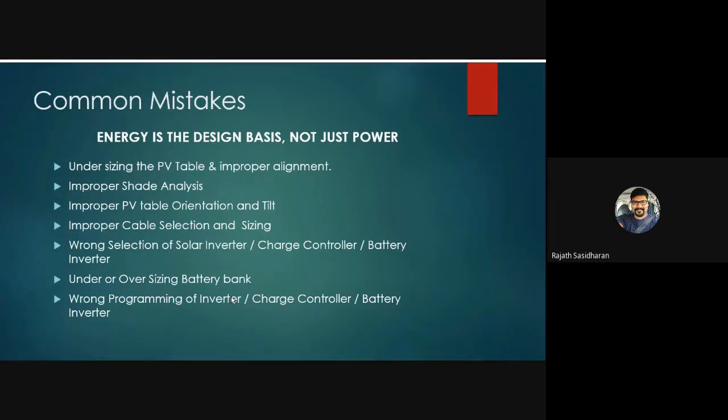Wrong selection of inverter. You have 10 panels and you are not able to connect them to that solar inverter. That's a problem. So you need to make sure that the inverter is chosen according to what type of solar panels, what the wattage of the panel is, and how many panels you are intending to connect to it.